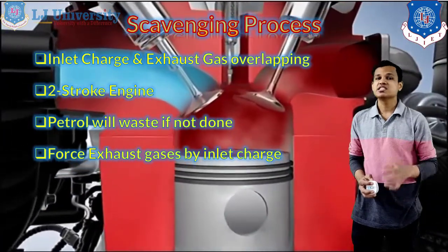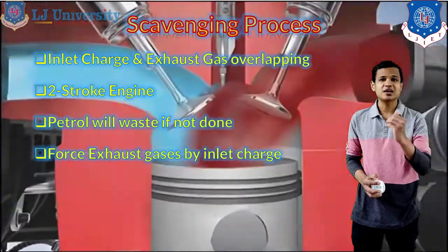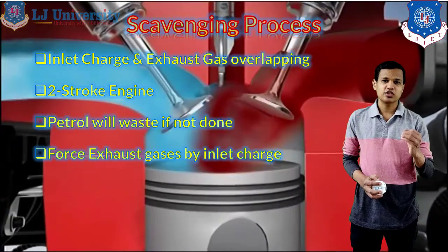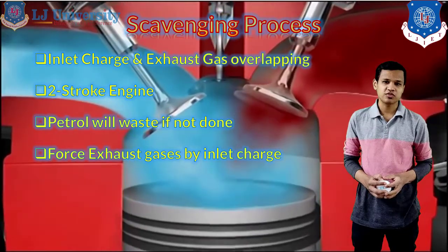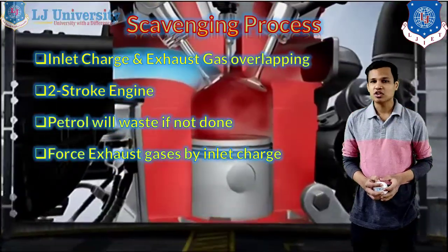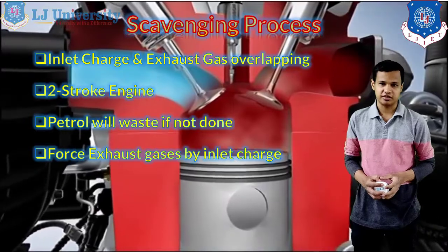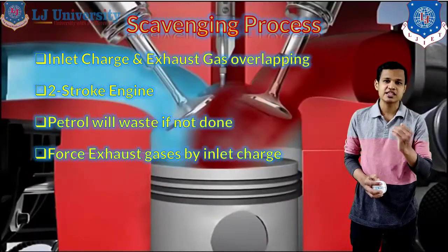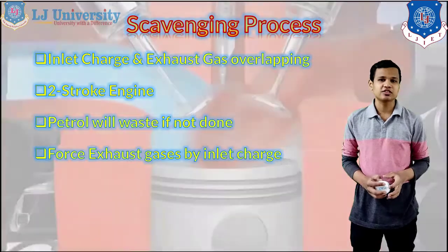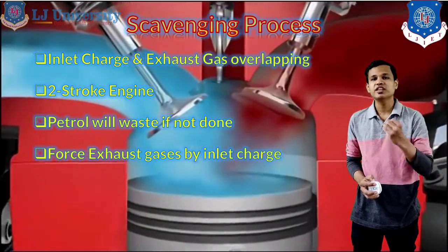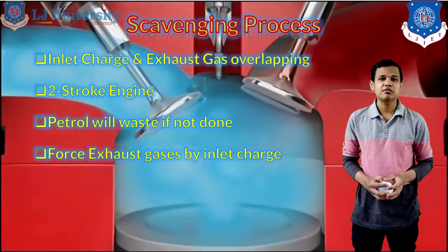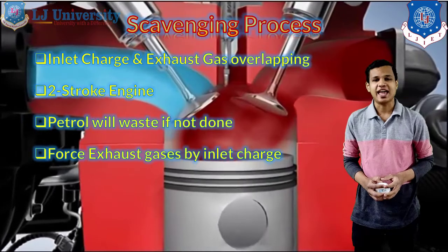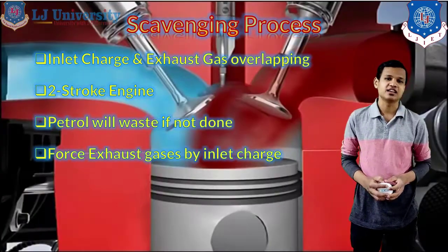In the case of the diesel engine, what we are supplying is only compressed air via the transfer port or the inlet valve, right? So if the air goes out with the exhaust, there will not be much of a problem, because fuel will not be wasted. Scavenging will also be done in the diesel engine to force out the exhaust gases. But if we are losing air, there is not much problem, because we are not losing diesel, we are only losing air during the process in the diesel engine.